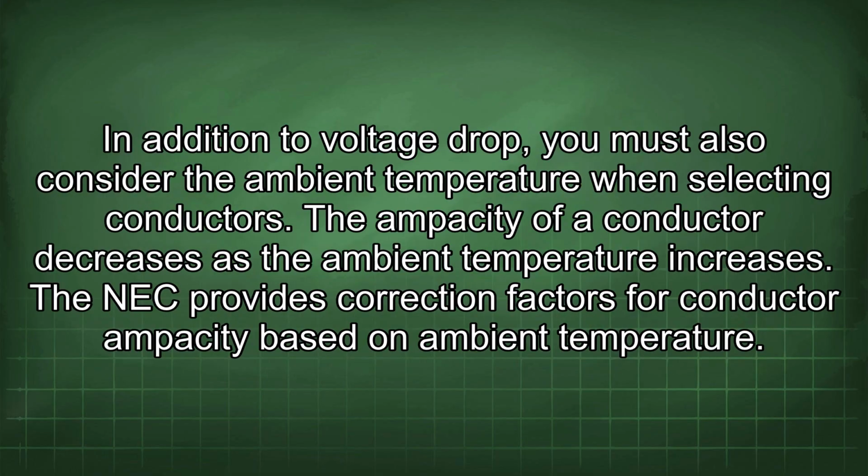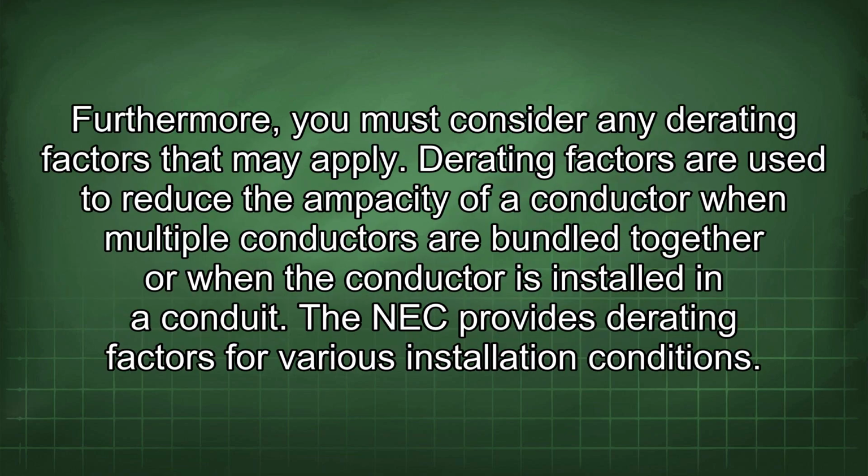In addition to voltage drop, you must also consider the ambient temperature when selecting conductors. The ampacity of a conductor decreases as the ambient temperature increases. The NEC provides correction factors for conductor ampacity based on ambient temperature. Furthermore, you must consider any derating factors that may apply. Derating factors are used to reduce the ampacity of a conductor when multiple conductors are bundled together or when the conductor is installed in a conduit. The NEC provides derating factors for various installation conditions.